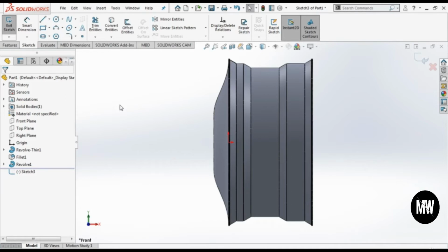As you can see here on the video, the last cut extrude was really bad and I didn't know how to deal with it. It's a big problem because I used the wrong features to get the form that I need. So in order to avoid any problem, the combine is the solution for any problem. So here let's get first the form of the revolved base that we are going to subtract from the wheel, and after that we will see how to use the combine. So let's go and let's create the sketch.